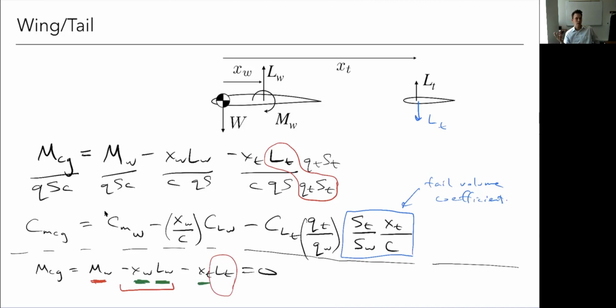Usually that increase in drag that we pay, we call it trim drag, because there's increased drag, both because the tail creates its own induced drag, but that also changes the lift that the wing needs to carry, which increases its induced drag. And we usually put that together and call it trim drag. It's just extra drag we need to trim the airplane out to get it to zero moment. Okay, so the lift of the tail is lifting downwards.